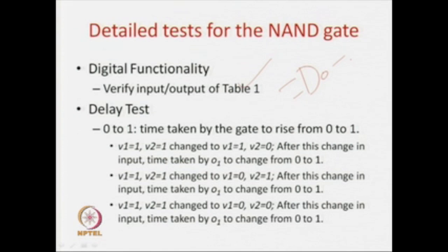So, all this speed will depend on the delay, that is, if some input arrives here and some output arrives here, what is the time delay of this gate? If this gate has a very high time delay, obviously the whole circuit, which will be composed of so many small gates, will also be slow. And if you want to go for a minimum delay, or you have to increase the frequency or the performance in terms of the speed of your circuit, these gates should have a lower delay. So, delay is a very important parameter in case of circuits.